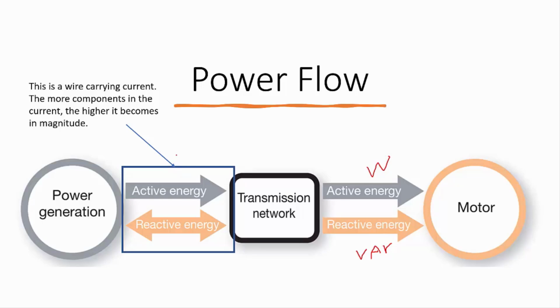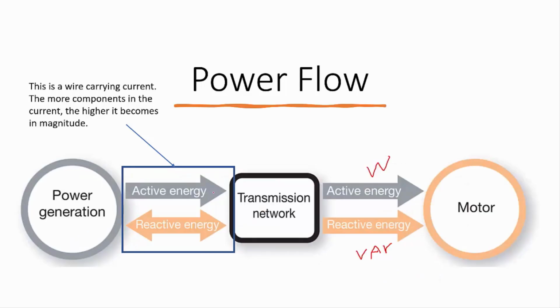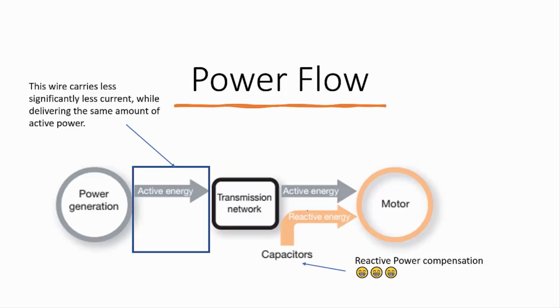So, what would be an ideal solution for this particular problem? I can replace the reactive energy flow between the generation and the network with reactive energy that is locally generated and fed to the motor.